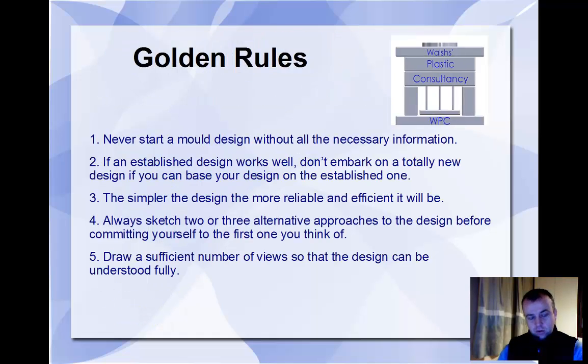Some golden rules for starting your mold design: never start a mold design without all the necessary information just outlined. Just on that, if there's a design that you know works well, that you're used to working with within your factory, try to stick with that design.